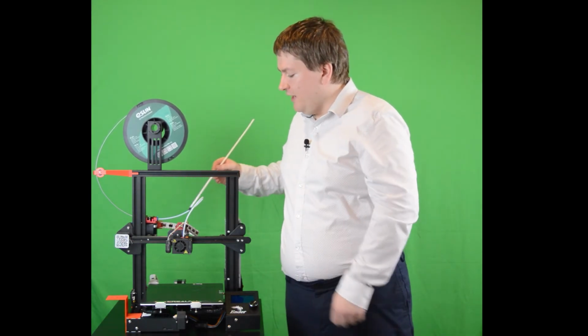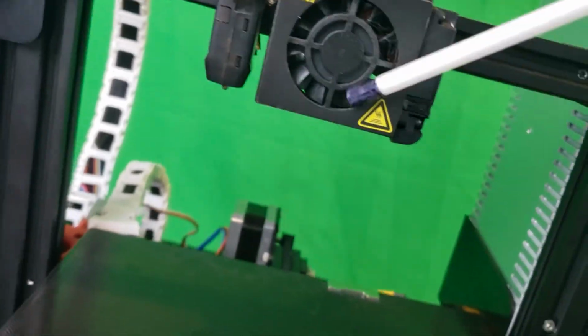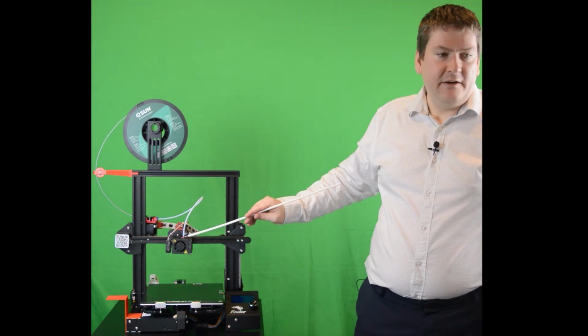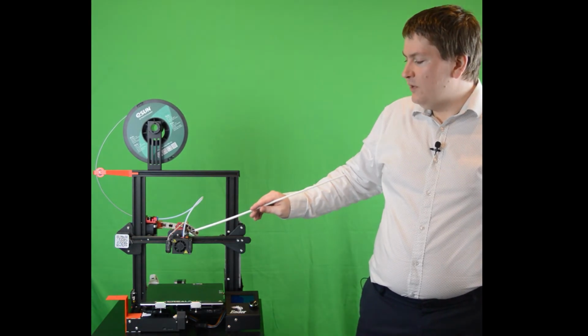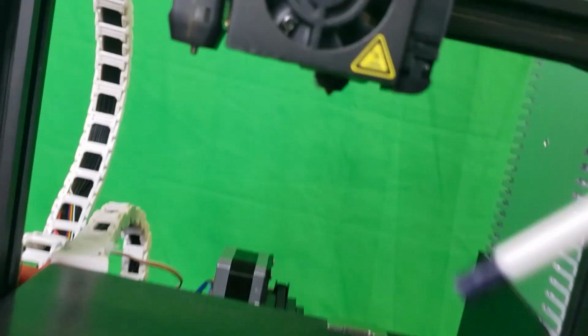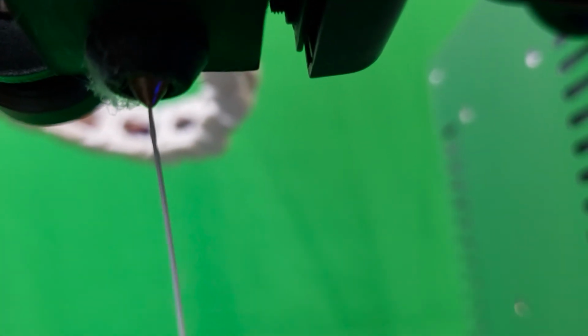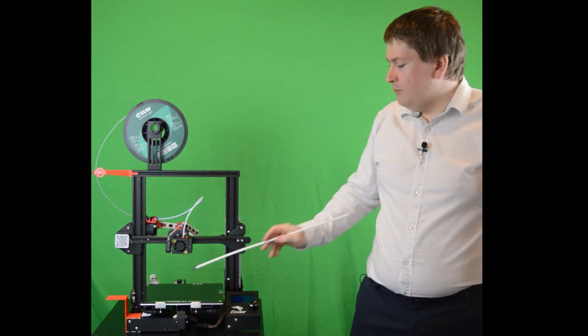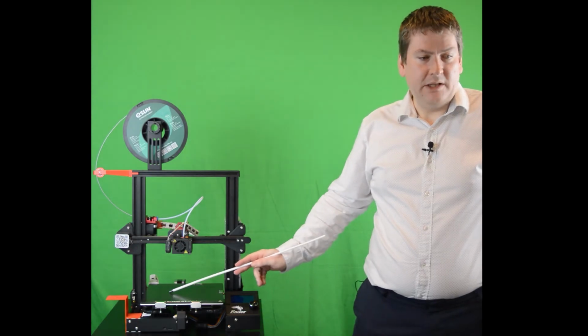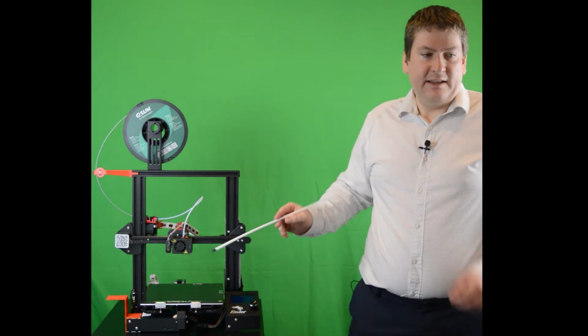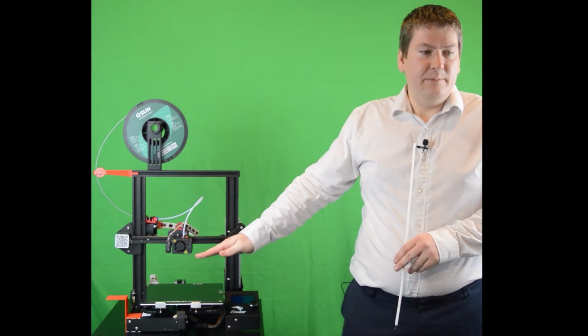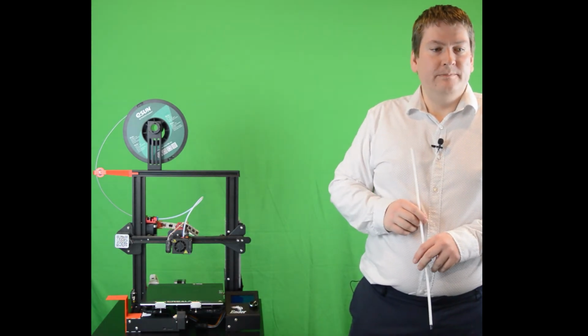And it basically just guides the filament down and into this print head. So this is what we usually call the hot end. And it has a heating element in here and some fans that allows it to melt the plastic. And then at the bottom right here, we have a little nozzle that shapes the plastic into a very thin line, usually about 0.4 millimeters, and then prints it onto this build plate. So this is a heated plate that lets the plastic get a good stick to it, and then it puts down layer after layer of plastic, building it up until you have your object.